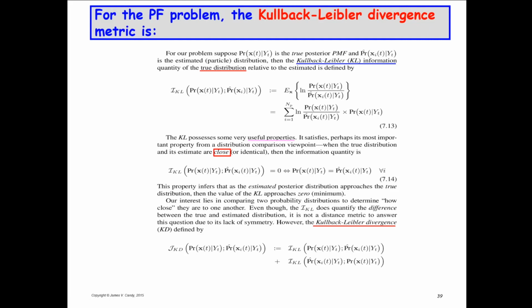Well, for Kalman filters, we know that, at least for the linear Kalman filter, that it's optimal if its residual sequence is zero-mean, meaning white. So we can perform statistical tests on the innovation sequence. And this is what I was talking about before with fitting the polynomials, etc. If the model is matching the data, then all you see is an uncorrelated sequence, a white sequence, and everything has been removed by the model, all the correlations. So in a sense, the model's fitting the data. Well, that's what the Kalman filters do. And people do that for both the linear and nonlinear filters. And it tells you that the model is fitting the data and it's valid.